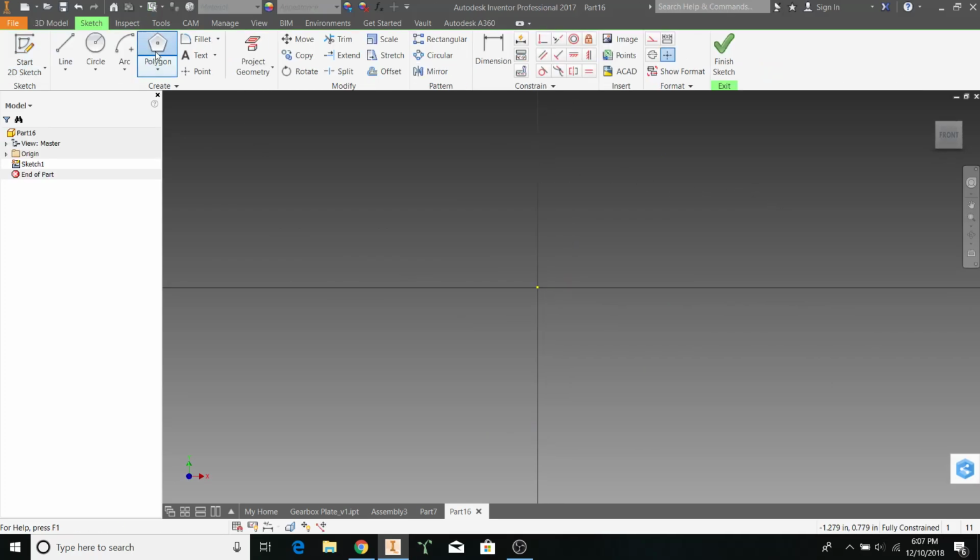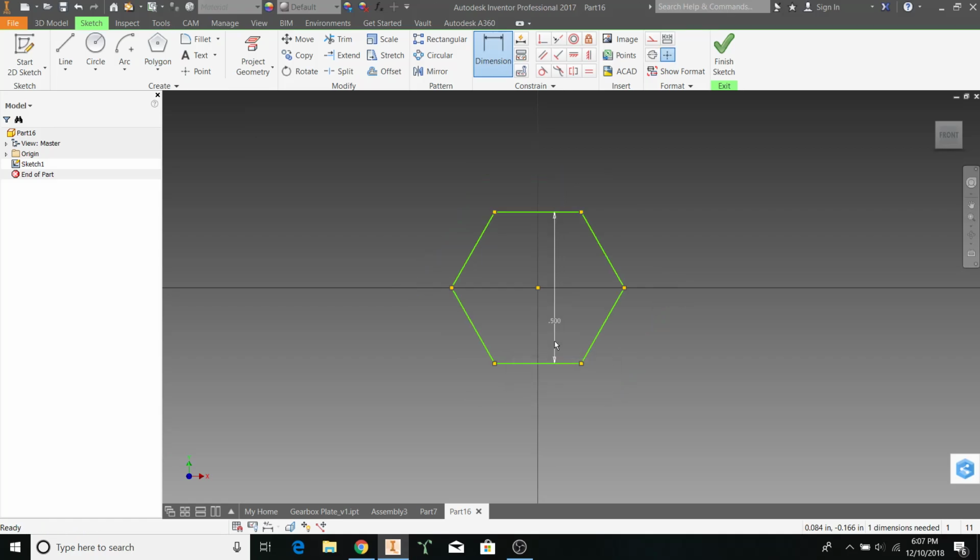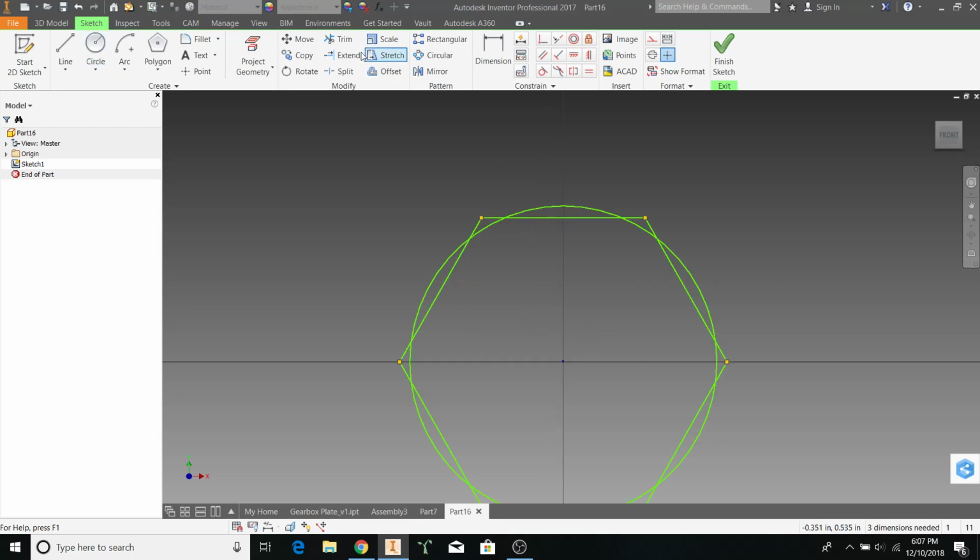Now, typically on our team, we'll be using Thunderhex to make our standoff. You can check this drawing on the Vexpro website, but I have it memorized so you can follow what's in the video. 0.5, and the corners are rounded to a diameter of 0.5414. Let's delete the dimensions and trim off the excess.